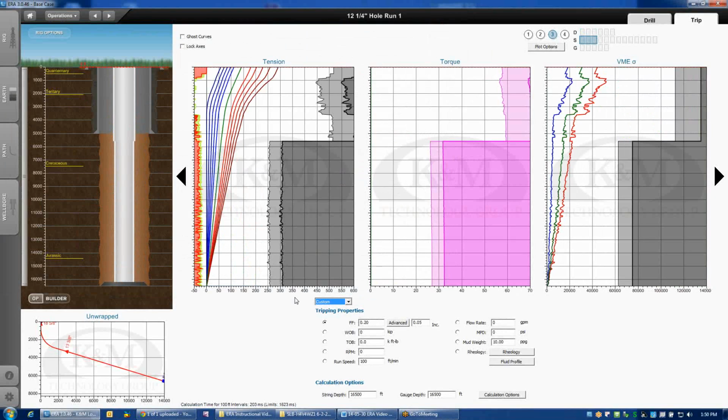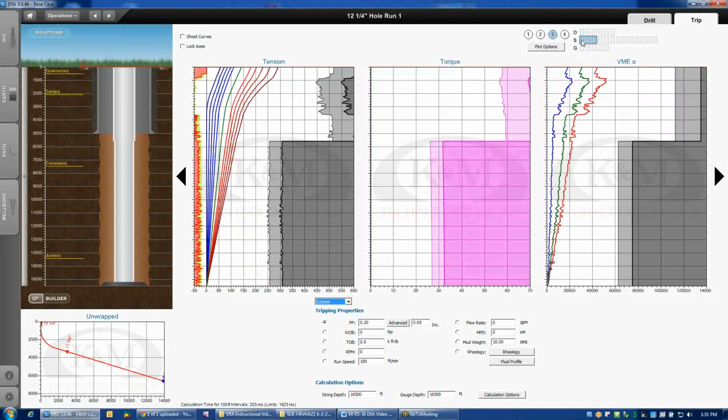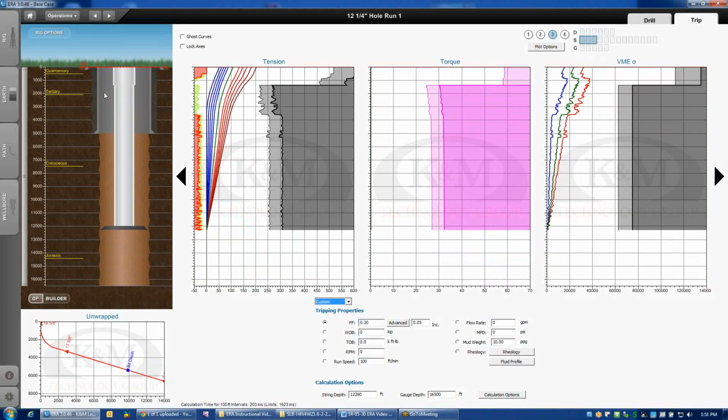Notice that the snapshot shows me that I am very much closer to the loading in the tube down here in the E pipe than I am in the S135 5.5 pipe. Now, where does that come into play? If we go back to the driller's view plot, notice how we have this kind of stepped curve as the string is moving down in the wellbore. What I'll do is come back to the snapshot, and we'll watch how the loads change depending on where the 5-inch is located. Of course, here's the crossover. That's where the 5-inch is.